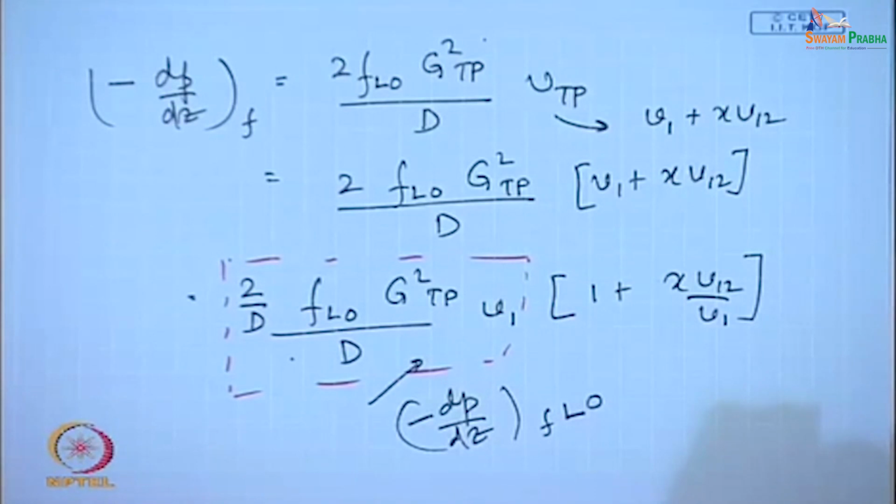So, how does it simplify the situation? In that case, we can just take liquid at the total mixture flow rate and allow it to flow through the same pipe. Under that circumstance, finding out the pressure drop or the pressure gradient becomes very easy. Yes or no?